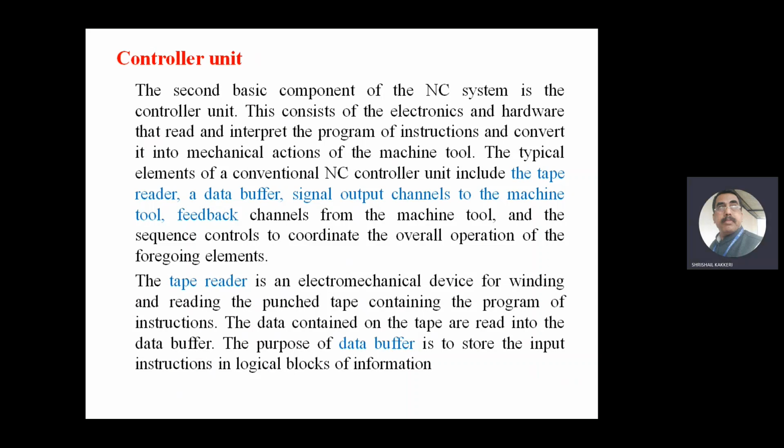You can see this. I have given an input of 30-degree rotation. Just simply I am telling you, here this is the machine system. It will be rotating by 30 degrees, how much we don't know. And once after that, the feedback system, the stepper motor, will be finding out how much it has been rotated. But definitely, there will be small backlash in the mechanical systems, small errors in the systems, okay?